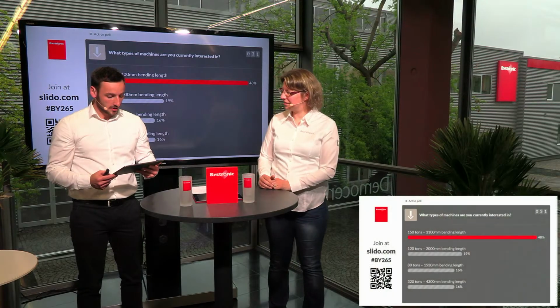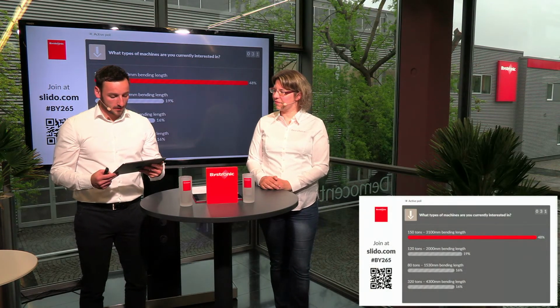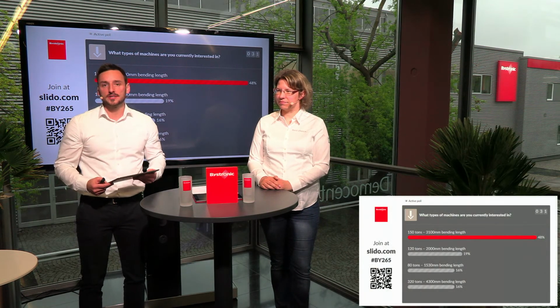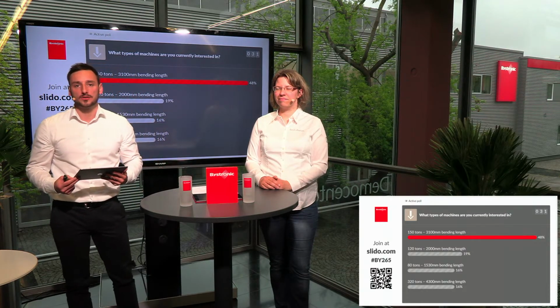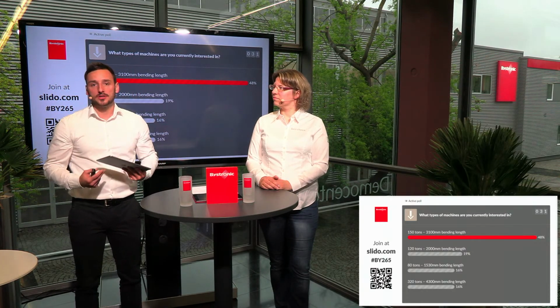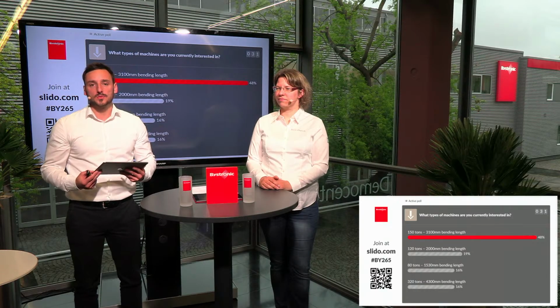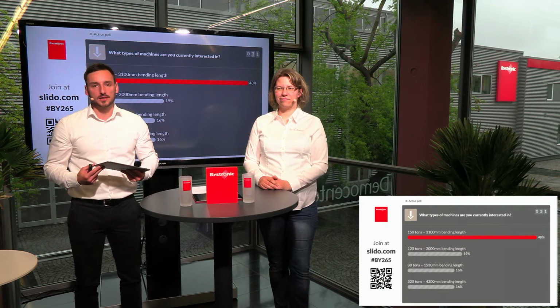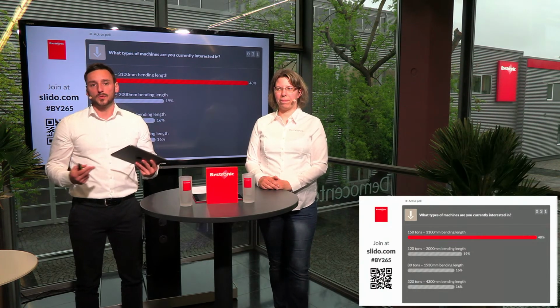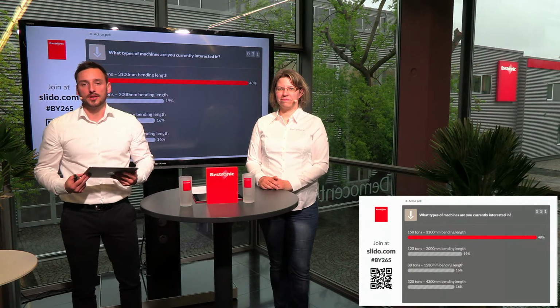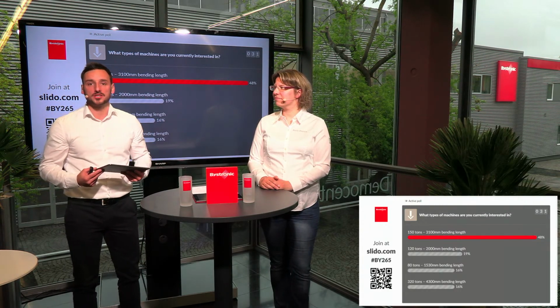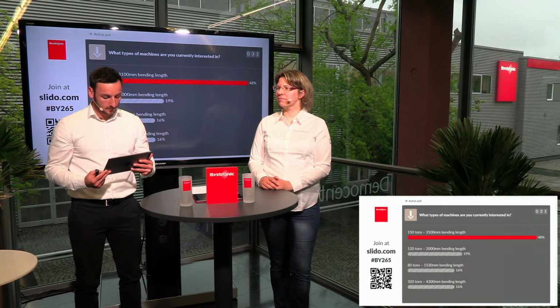Again, thank you, Ronny, for your presentation of the modular tool changer. We have already seen we have some questions in Slido. One question was whether the laser angle measuring system can be used with 85-degree dies. Yes, you can use it with 85-degree dies, especially for mild steel, but we recommend using 30-degree dies because of much higher flexibility.